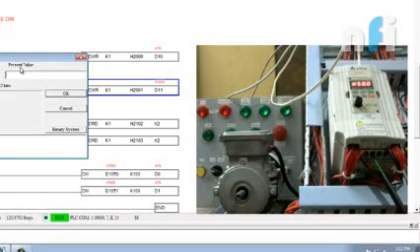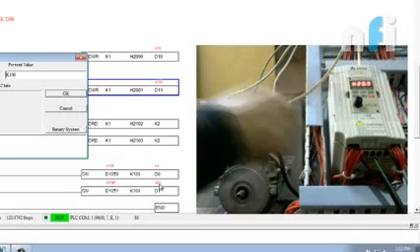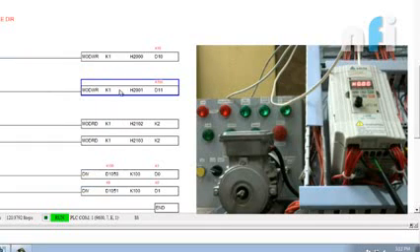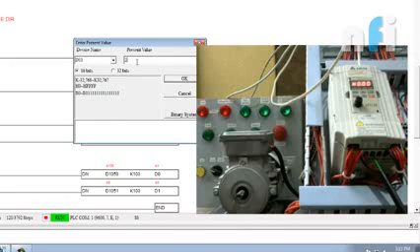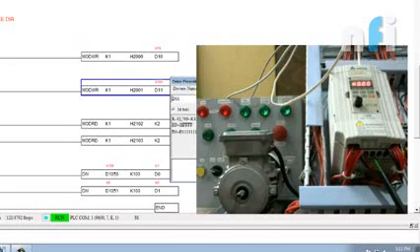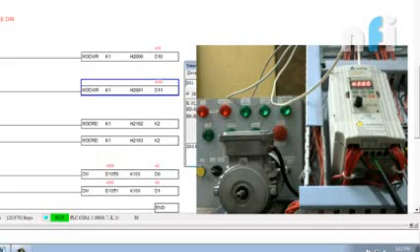So let me just change the frequency. You can see that both are getting changed proportionally. I'm putting here K100, 1 Hertz. Can you see here it is decreasing, and in a similar way it is decreasing in the drive itself. Now it's going to 1 Hertz. Okay, which I guess the drive will not take at 1 Hertz. I have to put some more value. Wait. The drive requires a minimum value to run, and 1 Hertz is not enough.